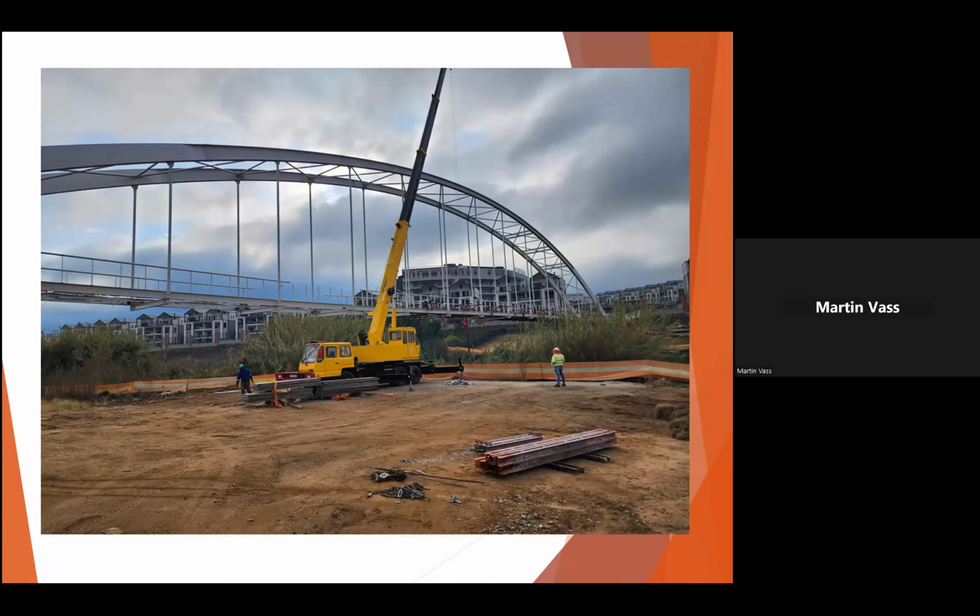At the time of the event, the abutments were cast, the steel bridge was in place, and they were casting the concrete deck from one side, here from the left-hand side going across. When they got about a third of the way across the concrete deck, the whole bridge buckled. They immediately stopped pouring the concrete. Then they started to check the design. In the meantime, they demolished the concrete, but the bridge was badly distorted.